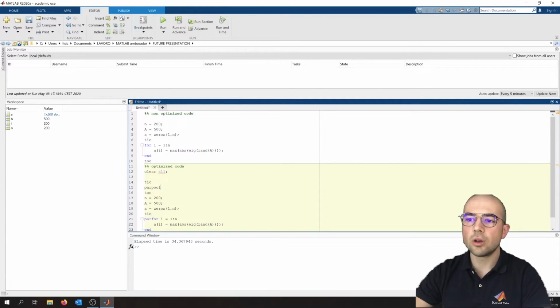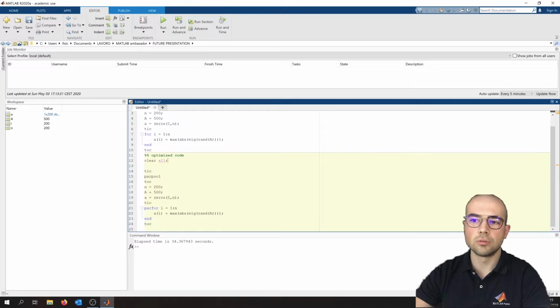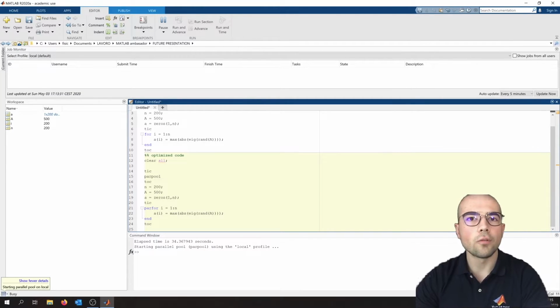Okay, moving on, I can clear all, first of all, to be sure that all the steps are the same. Okay, and then I can run some code. Let's start, and I will explain this. Clear all, you know exactly what it does. Now, tic toc takes the time, and we select here parpool. What is parpool? It's one of the 3 types of initialization of the parallel pool.